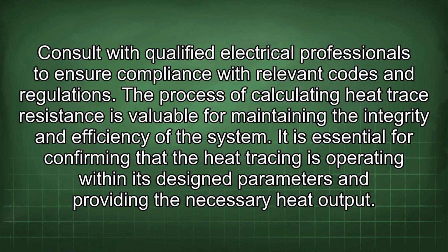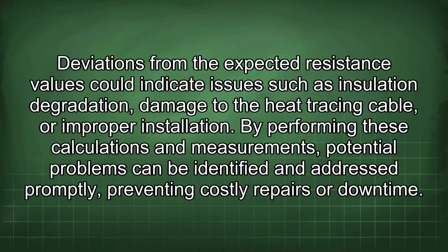The process of calculating heat trace resistance is valuable for maintaining the integrity and efficiency of the system. It is essential for confirming that the heat tracing is operating within its designed parameters and providing the necessary heat output. Deviations from the expected resistance values could indicate issues such as insulation degradation, damage to the heat tracing cable, or improper installation. By performing these calculations and measurements, potential problems can be identified and addressed promptly, preventing costly repairs or downtime.